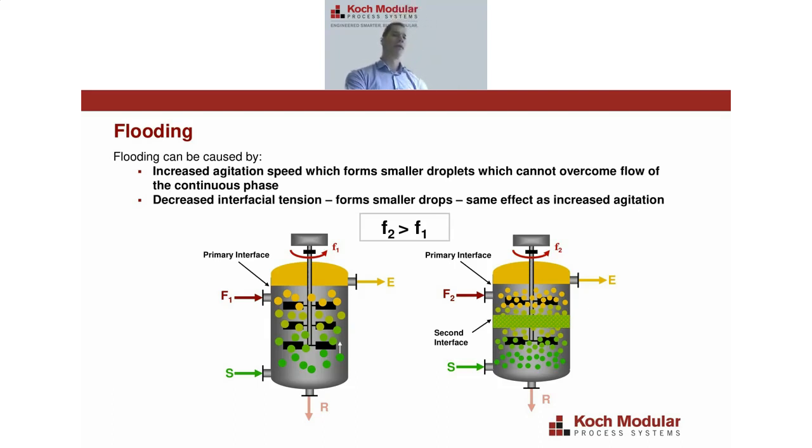column. Also, typically extraction columns operate at their highest efficiency as you approach the flood point. So just by pushing the column to the flood point and backing off when we're running a pilot test, we'll be able to operate the extraction column under its most efficient conditions, at least from a capacity and agitation standpoint.